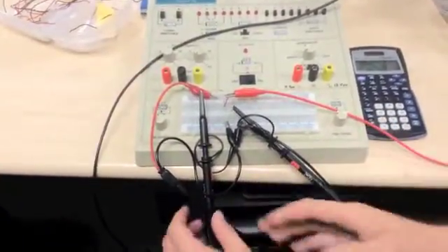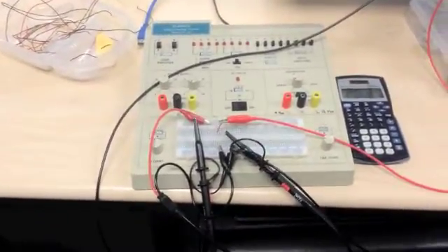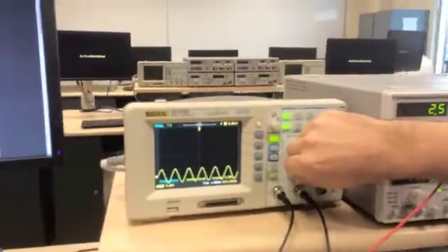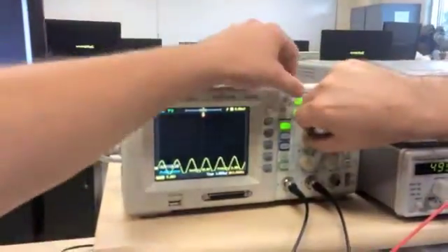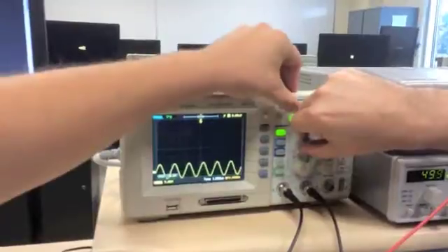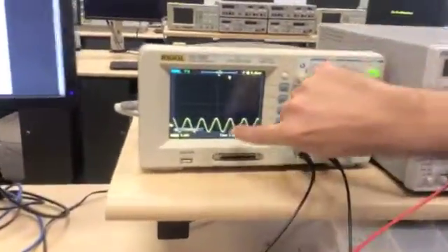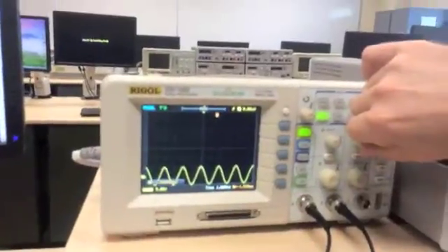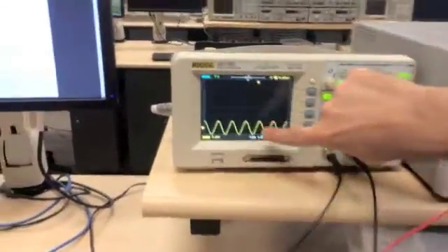Both of our probes have been inspected and they're both set to the 1x setting. And now we're ready to measure. With this vertical position, I can change the scale. I can bring the bottom of the waveform to the bottom of the display, and then I can adjust the horizontal position so that I can read along this axis with the dashes the voltage peak to peak. So in an old school calculation, we count divisions.